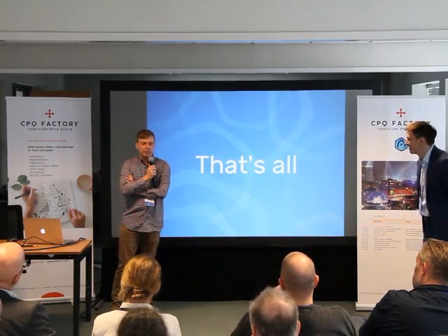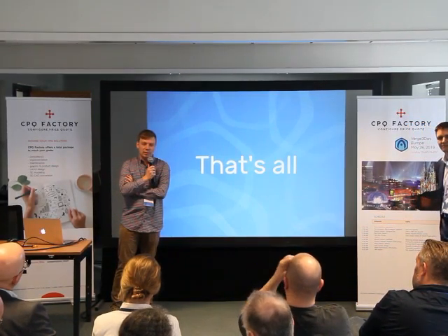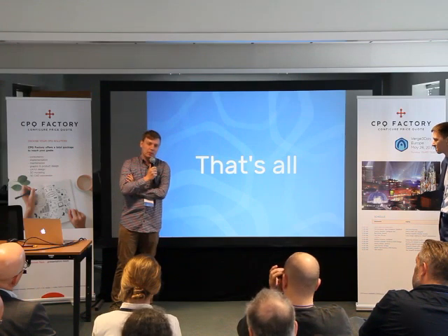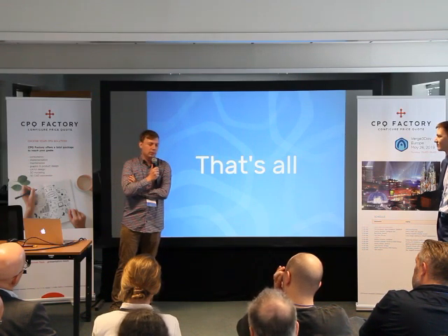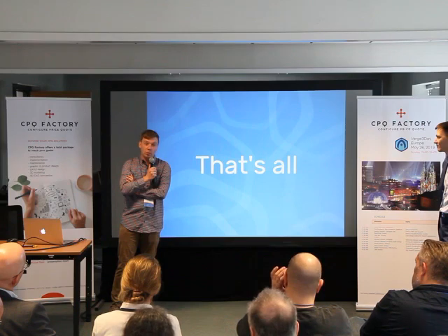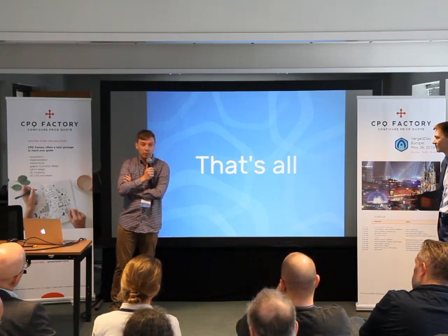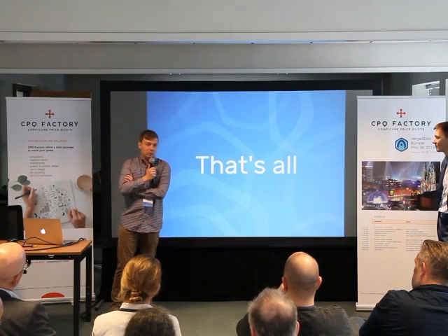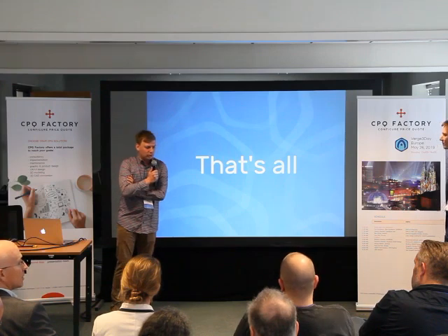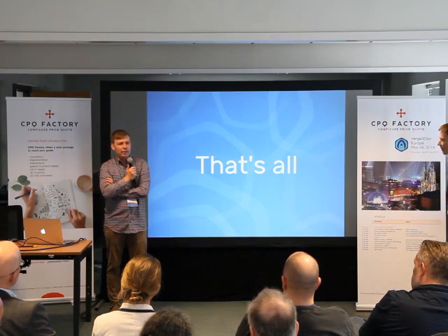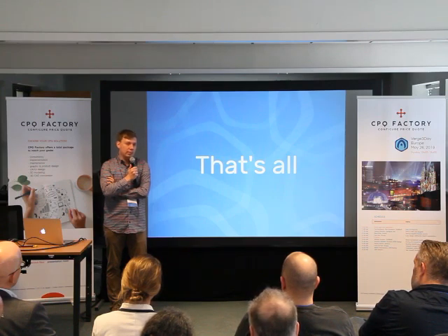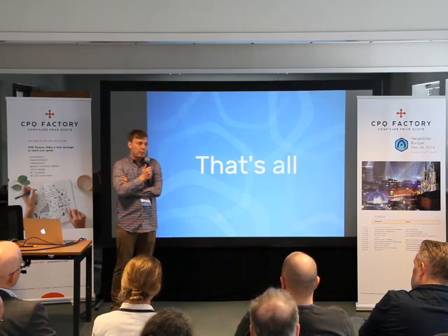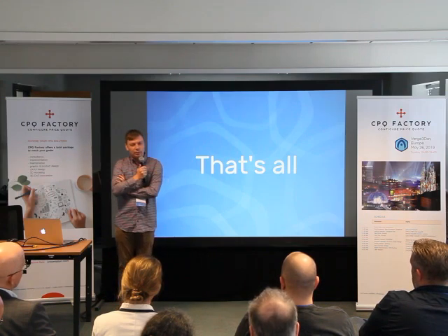Decimate from time to time does not give a good result, so it is better to use polygons for good shading of the object. Decimate gives very triangulated objects. Triangulated objects are not good for shading, especially if you leave it as a mesh without baking from high poly to low poly. If you bake from high poly to low poly, decimate is good enough.